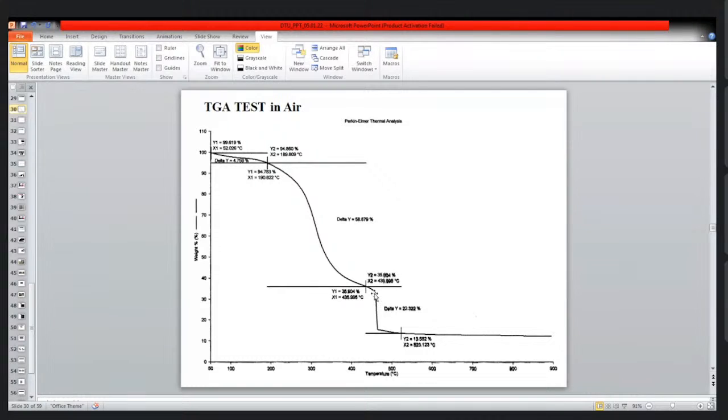What is coming out of the sample is observed here. It will provide us the entire idea of the rate of release of volatiles, the rate of char formation, the rate of char conversion into gas, and the ash residue. So it will provide many useful pieces of information. This information may also be useful to derive the chemical reaction rates.